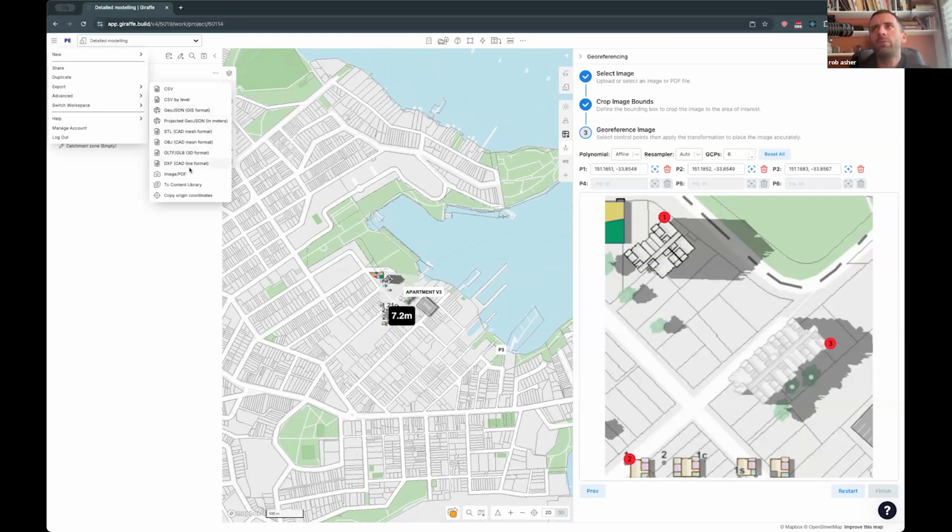So if you're after geospatial formats, we export GeoJSON, and my normal workflow for geospatial land is GeoJSON into QGIS, and then QGIS goes into a shapefile, KMZ, GeoTIFF, and all the rest of them. QGIS is free, very robust, very fast, very simple, and very widely used. So that's the way to do it for any formats. But we'll have a look at adding KMZ because I think that's an open one, should be easy.